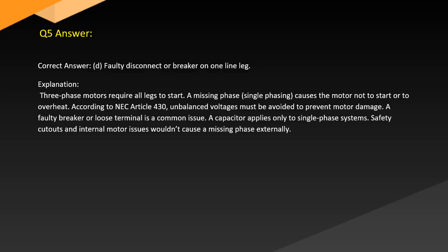Answer. Correct answer: D. Faulty disconnect or breaker on one line leg. Explanation: three-phase motors require all legs to start. A missing phase, single phasing, causes the motor not to start or to overheat. According to NEC Article 430, unbalanced voltages must be avoided to prevent motor damage.